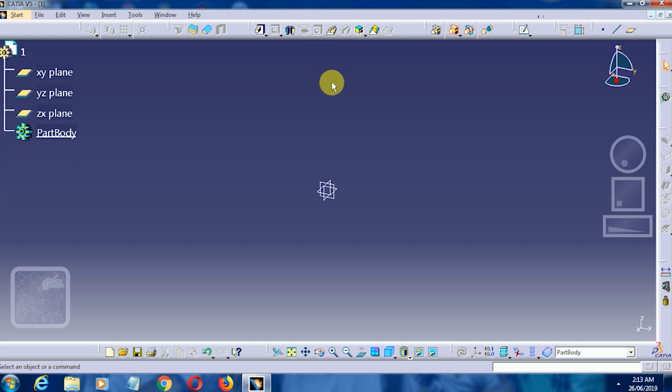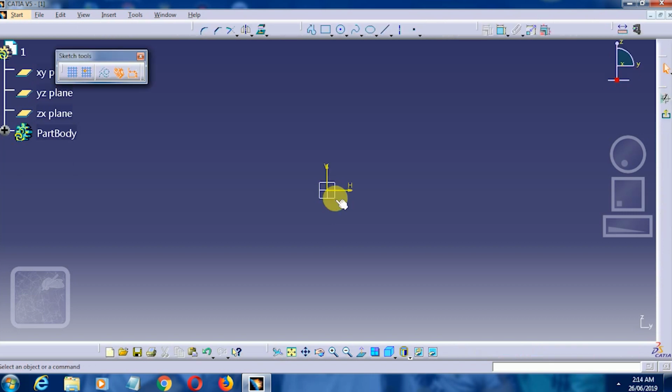So going through that, I have to open up one of the planes. You simply have to go on one of the planes. It will get highlighted here. The basic step is you go in the sketcher feature. Here you have two options: a simple sketcher and a positioned sketcher. Now, what do these options mean? If I choose only the first option and sketch, a particular plane will open up at 90 degrees, parallel. As we can see, I click on the plane and it opens up directly.